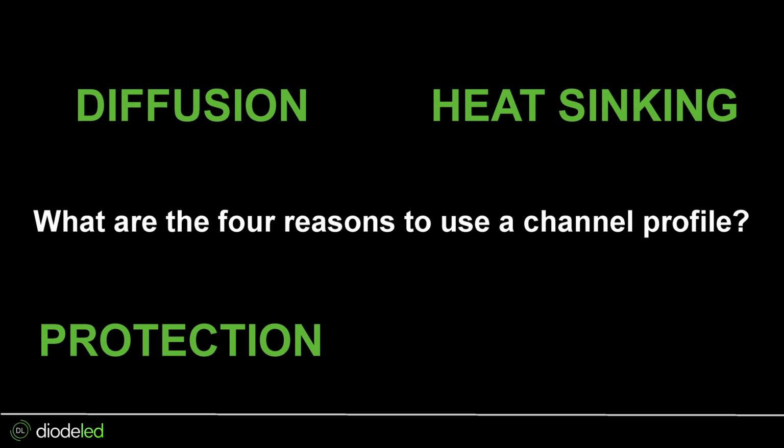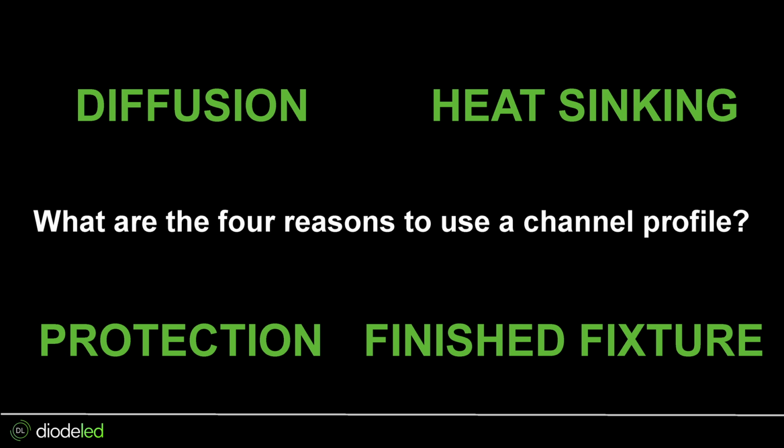Also protection. So protection from the environment, different types of elements, oils that splash up from cooking, dust, all these things that will collect on the exposed tape light if you don't have a channel and then sit on the phosphor and actually deteriorate it over time. And then the 4th one is not as well known, but it's probably my favorite, is a finished look or finished fixture or aesthetics. So this is really where the evolution of linear lighting is going, is being able to showcase really unique channel profiles that can integrate into architecture, but also look aesthetically pleasing, that have a very minimalistic, small form factor. And so that is what's awesome about a channel profile.